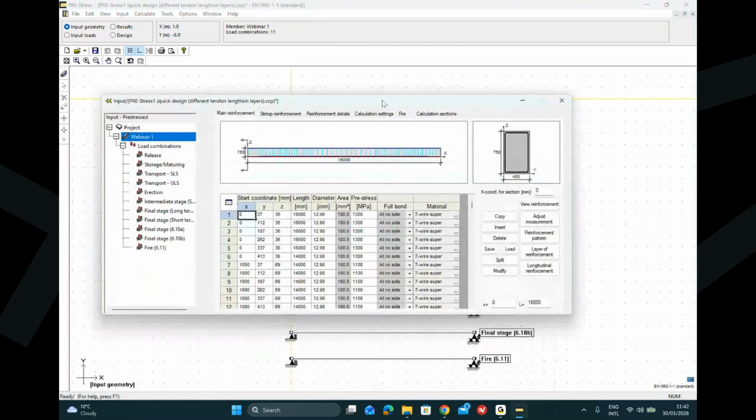So in this particular model, I have different tendon lengths. As I said, if you remember the first model that we did from zero here, the compression check was not satisfied, meaning that our tendons were pressing too much, so that it exceeds the compression strength of my section. And when that happens, usually in reality, we place some non-adherent tubes in the beams, and we move the second row of tendons, for example, to a different section.